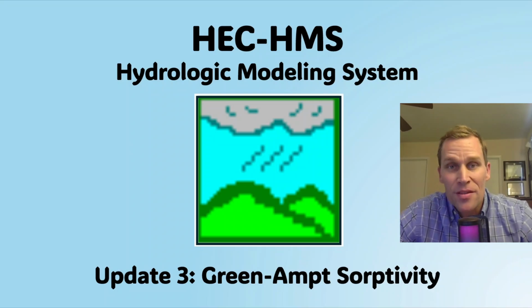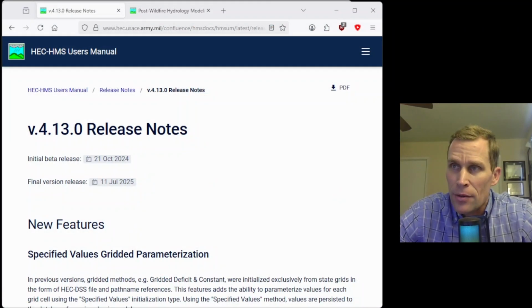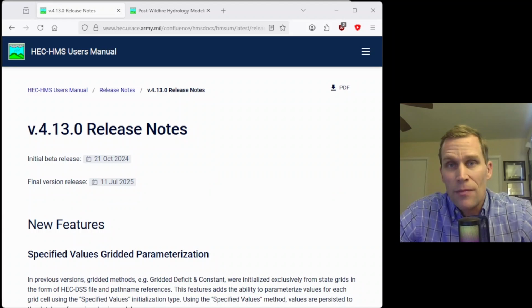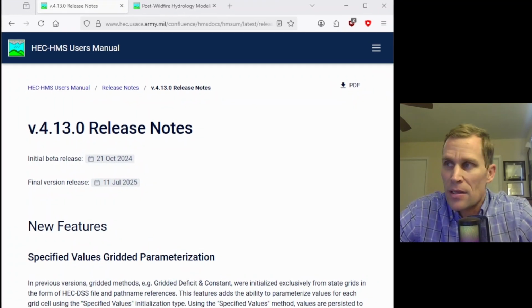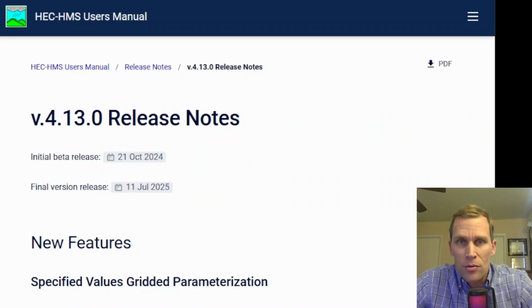Welcome and hello. This is an update video in HEC-HMS, and I've titled this one Green-Ampt Sorptivity. This is a new option in the Green-Ampt loss method. The Green-Ampt loss method now has a second capillarity parameter option called Sorptivity. The first option, available in previous versions of HMS, is called the wetting front suction. So we're going to walk through a tutorial in this video to demonstrate this new sorptivity feature in the loss